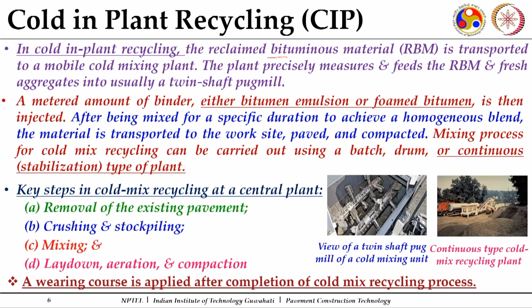So, the amount of RAP which is generated, if there is presently no facility to go for in situ recycling, or the amount of reclaimed material is more than what can be used, a good amount of reclaimed material will be stockpiled at the plants, some nearby plants. So, this is usually when cold in plant recycling will be preferred.